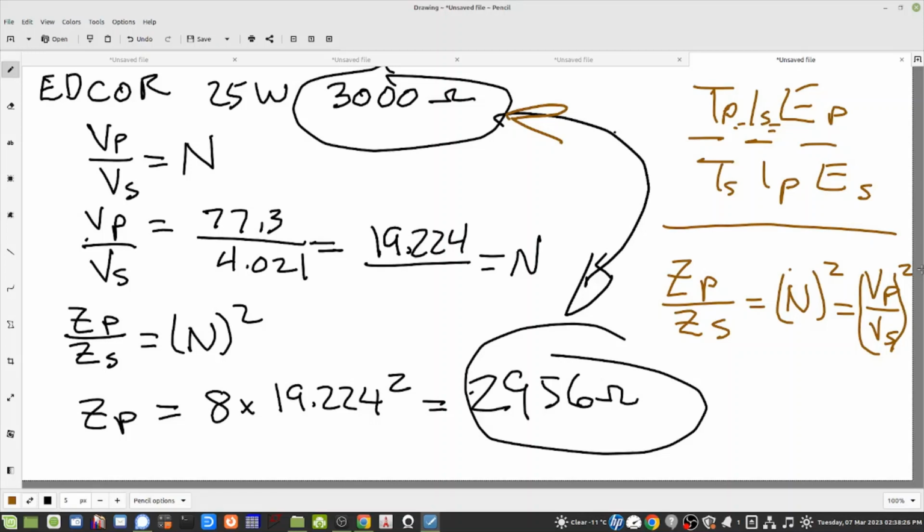In the next series, I'm going to talk a little bit about the maximum power transfer formula, and that gives you an idea of why you want to match your output load impedance to the one specified for the particular output vacuum tube you're using.